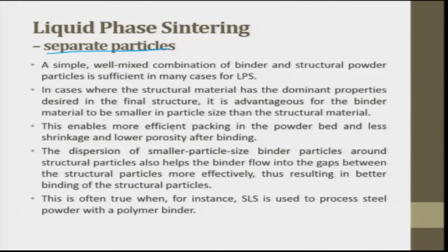This enables more efficient packing in the powder bed, less shrinkage and lower porosity after binding. The binder size is very small, so packing is more efficient, and there is less shrinkage because the particle that is going to melt and flow only later shrinks.